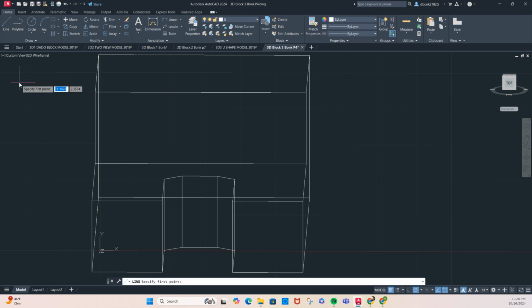Okay, this is a relatively simple cut. It's 3 inches and the cut runs down the center inch. So you're going to pick up one of these lines. Doesn't matter which one. You pick up a corner, start tracking in the direction you want to go. It's got to be over an inch. 1, enter, and then I can go down.